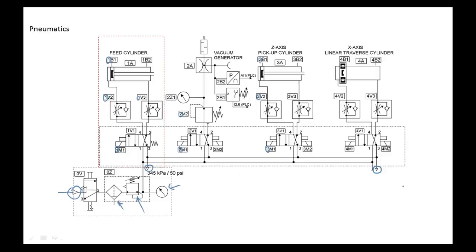With pneumatics, we meter out. Because if you meter in, the cylinder, when it moves, is going to have to recompress the air. It's going to move and recompress the air. So if we meter in on a pneumatic cylinder, and we might try that over here, you'll notice that the cylinder jumps. Well, what about a double-acting cylinder? With a double-acting cylinder you meter out, but we use 2 flow control valves. Yeah, so this is 2 flow control valves.